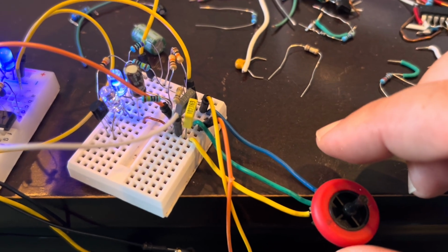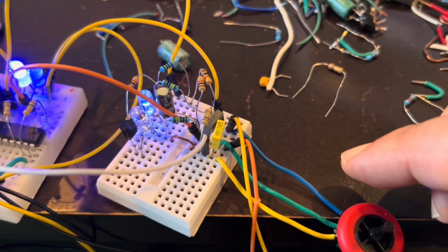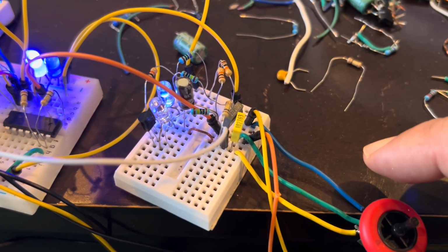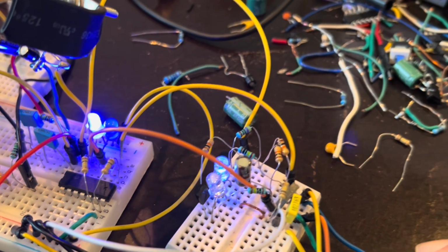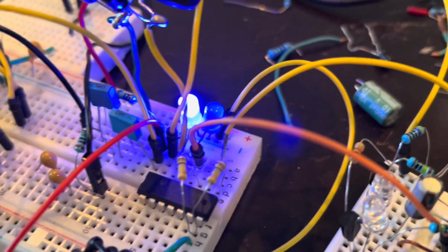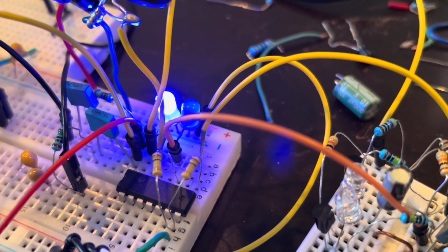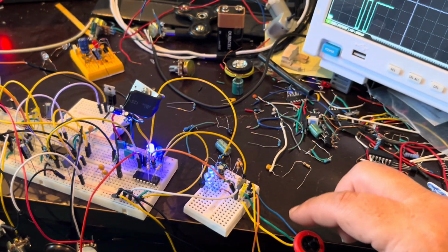And so if I have B as the clock pin, the rising edge of the clock will trigger the flip-flop to flip to the set mode when the data level is high. And so since the data level is high, which is the A pin, and the B pin is the clock, when I turn it clockwise again, that triggers it to set. And so what happens is the Q output, which is that light on the left there, goes on and it stays on. And so no matter how much I turn this, it stays on.